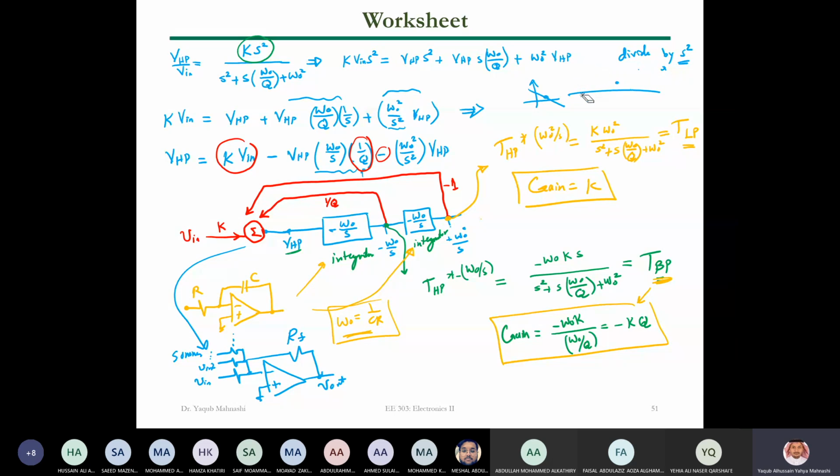At the end of the day, we want an integrator only. And in the low pass filter, you need to add another resistor in parallel with the capacitor. So yes, the answer is yes. It can be viewed as an integrator, but it's around the pole. Not at high frequency or low frequency. Around the pole.